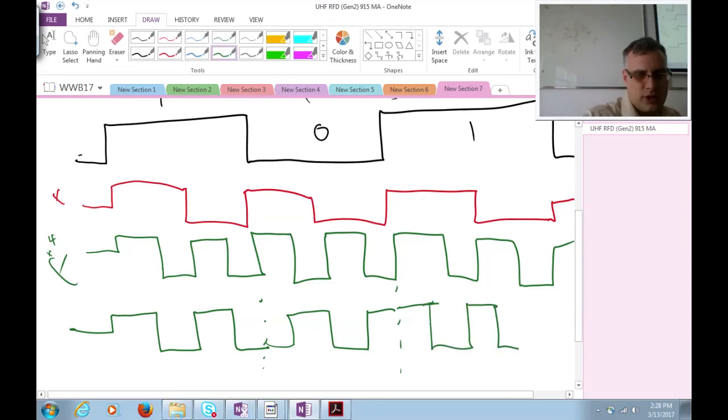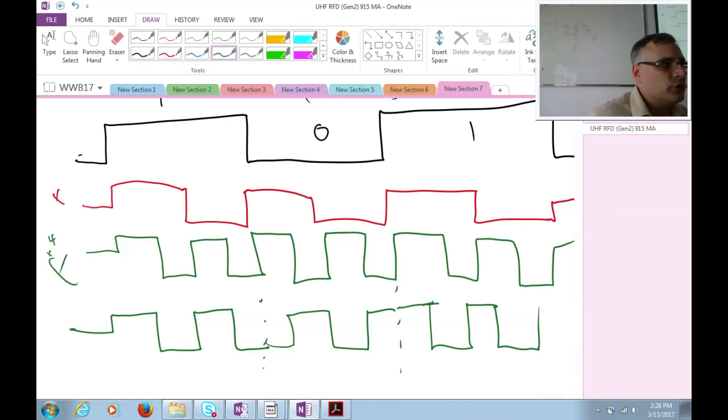Swallow a pulse at the transition. Otherwise, what I transmit is just a straight up square wave. And so you can do that as much as you want. You can have 20 cycles of transition in between every bit.